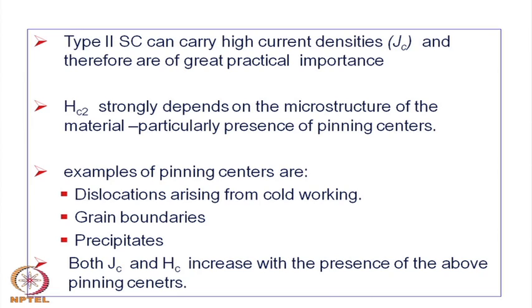What are the pinning centers? This also we briefly discussed. There are three varieties of pinning centers one can think of. One is the dislocations. Dislocations, as you have discussed previously in connection with the defect structure of the material, are crystalline defects. All crystalline materials are supposed to have some dislocations, and dislocations are basic defects which can control the plastic mechanical deformation of any material.